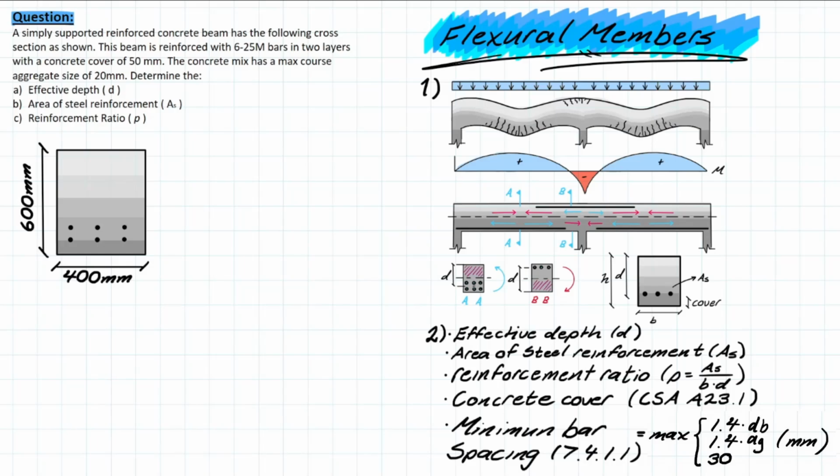Now, continuous structures like the one I've drawn here have three or more supports and require more complex ways to analyze and develop these bending moment and shear moment diagrams. And the one takeaway that we need to take away from this figure is that now there are inflection points. So you see, we have this bend or bow on the bottom and then hogging at the top.